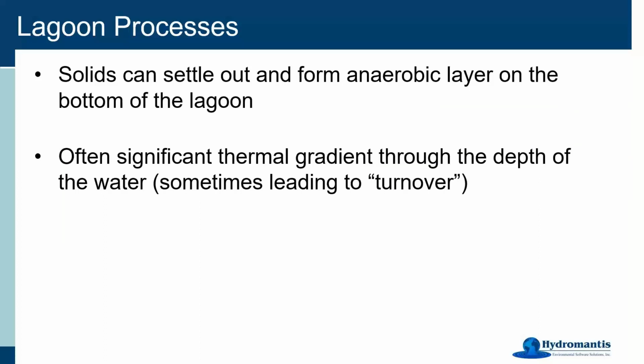So in addition to all of that, the solids can settle out and form an anaerobic layer at the bottom of the lagoon. That's possibly intended. Maybe the lagoon is there to actually do that final solid settling and remove that last little bit of TSS. Or maybe you don't want that to happen in your lagoon, so you have to have lots of aeration to prevent your biomass from settling out. But either way, you could theoretically have a lot of solids accumulating on the bottom, and therefore that needs to be part of what we're going to capture in the model.